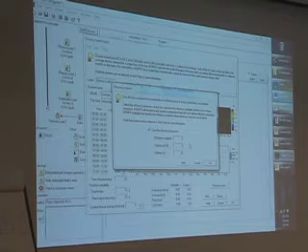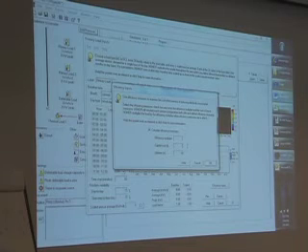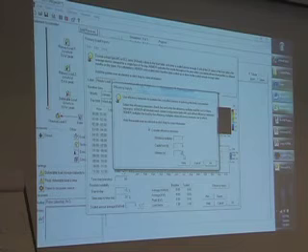So if we think that's going to save 30%, we put 0.7 there as a multiplier. What's it going to cost, to buy all those compact fluorescents or whatever it is. And to do the economics, we need a lifetime. So you're going to spend this amount of money for these more efficient appliances. We have to amortize that cost over a certain amount of time.